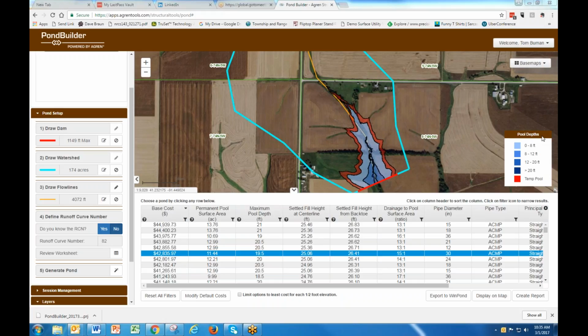We can track the sediment delivery, the sediment transport and erosion from the top of the hill all the way down to the stream. So if you're looking from a water quality standpoint at where the major sediment loads are entering a stream, this tool is very useful in helping you identify whether it's concentrated areas coming down in grass waterways or water and sediment control basins, or whether a filter strip all the way around your pond or stream is really going to help, or whether you need to focus on a few specific areas.